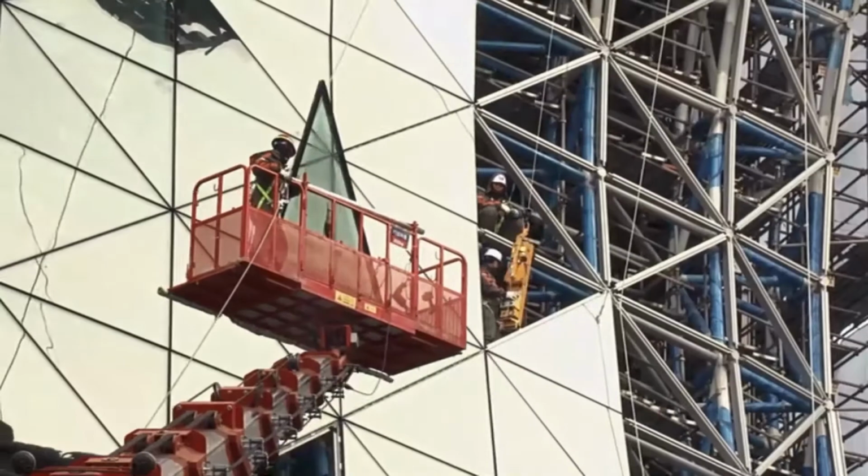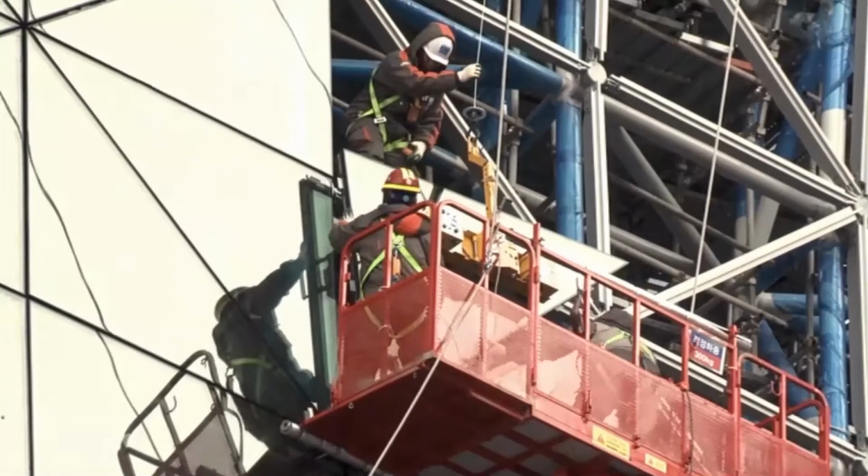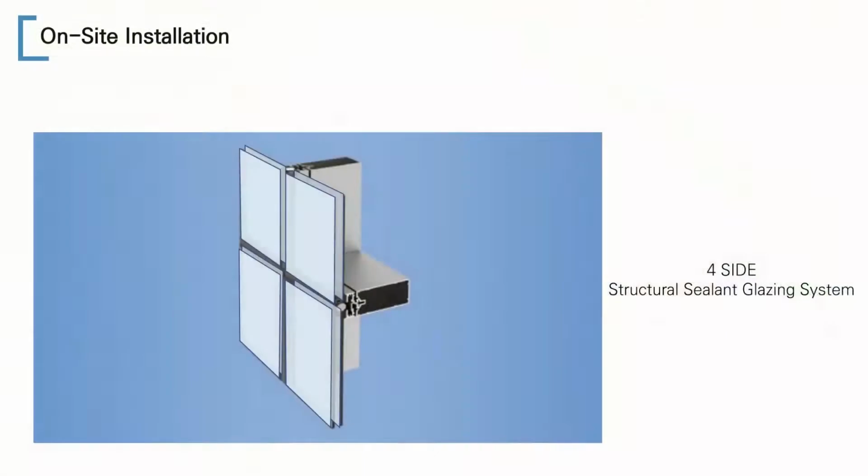Each crew member guides the position while pulling the glass with a press. Then they connect it with a clip. And they used the four-side SSG method for glazing.